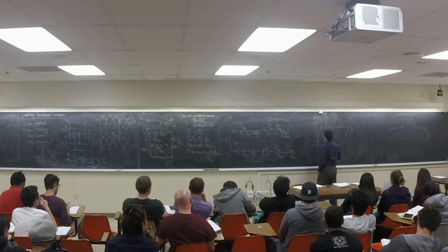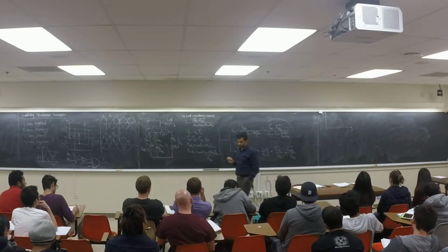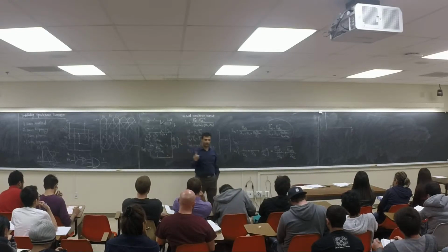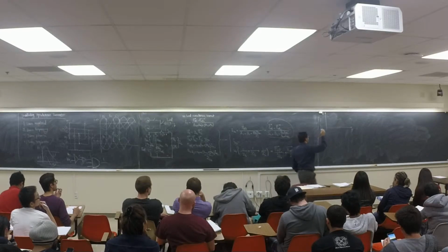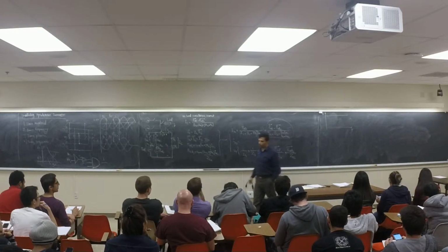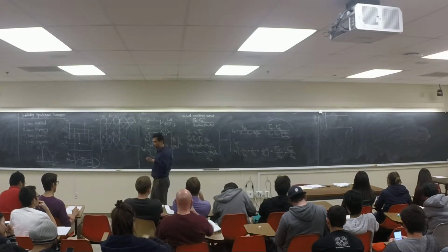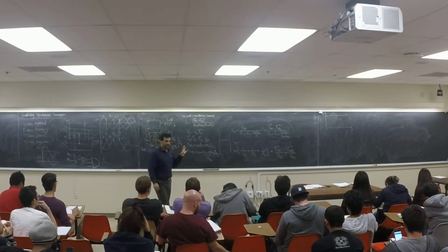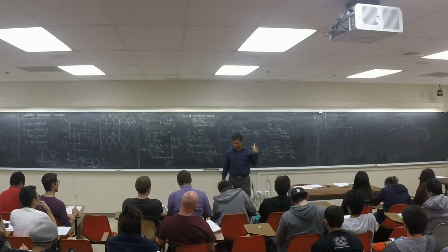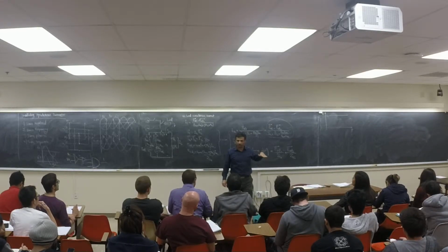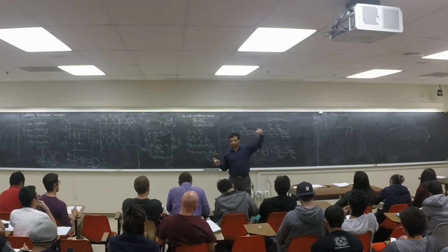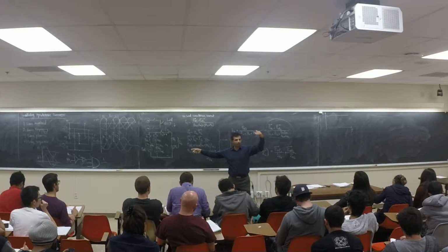This is a frequency versus power curve for a synchronous machine, right? If it's an ideal generator, what's going to happen? Frequency is going to be like this, right? Whatever power you're taking out of the generator, the frequency is not going to change. The generator is rotating at a fixed speed, right? Don't make a mistake. If the frequency changes, let's say from 60 hertz to 50 hertz, it's not going to change that much. But still, the machine is a synchronous machine, right? It was rotating at 60 hertz, 3600 RPM, right?